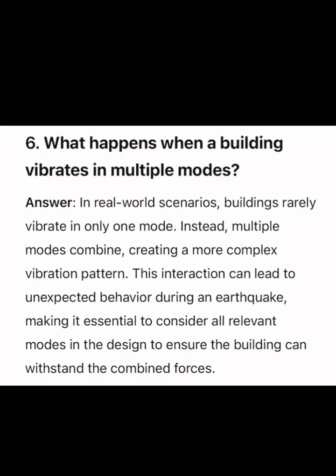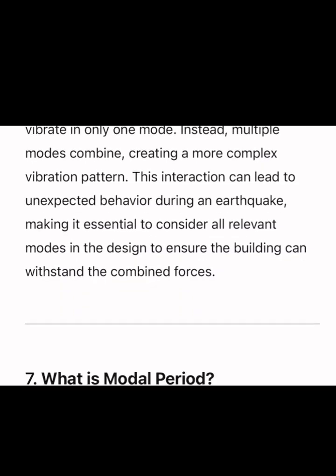So it's creating more complex vibration patterns. This interaction can lead to unexpected behavior during an earthquake, making it essential to consider all relevant modes in the design to ensure the building can withstand the combined forces. So we need to understand how the combination is going to occur and how this interaction between these behaviors is happening. We need to consider all the modes in our design so that we can design the building that can safely withstand the combined forces.